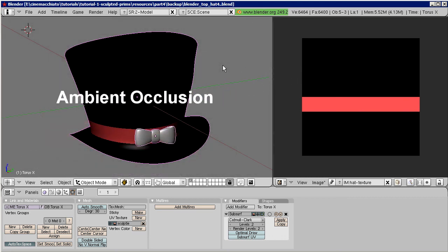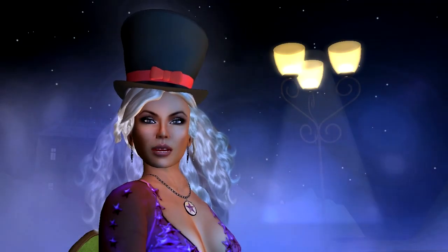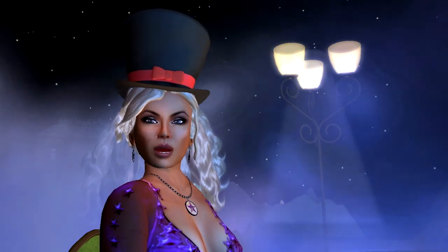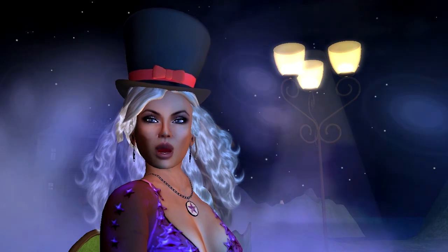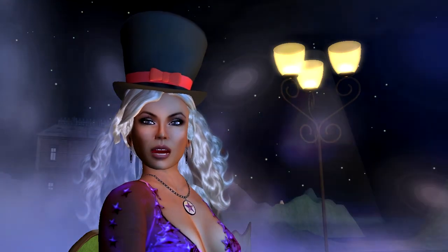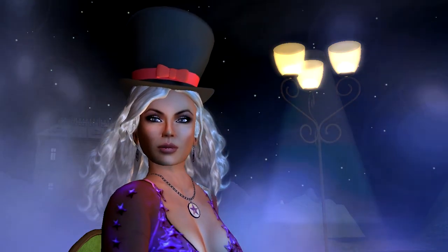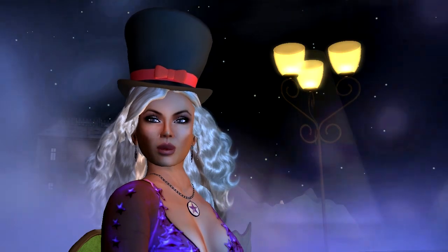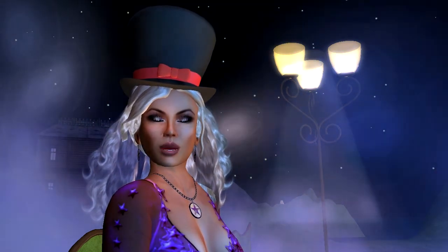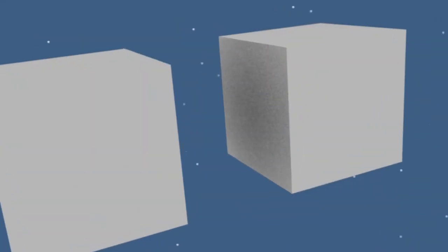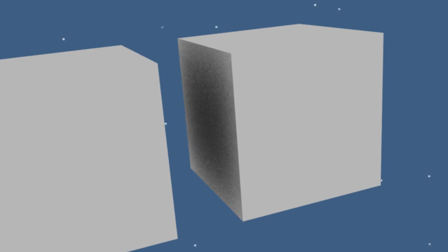Ambient occlusion describes the illumination of your scene with only ambient light. Ambient light has no recognizable light source. So if you're sitting in a space which is illuminated only by ambient light, then the amount of light energy getting to your eyes is not dependent of the angle of incidence. The only variation on light intensity can be introduced by occlusion, either from other objects or by self-occlusion.